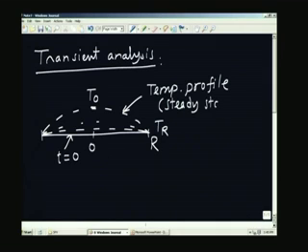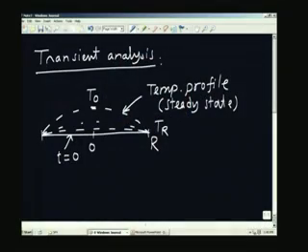So, when you subject the gauge to a transient by applying a step input in the form of a heat flux turned on at t equal to 0, initially the temperature is uniform and slowly the temperature profile builds up, and you can see the following.